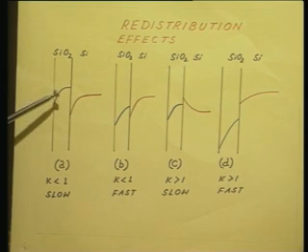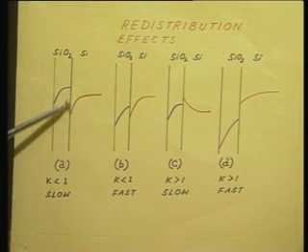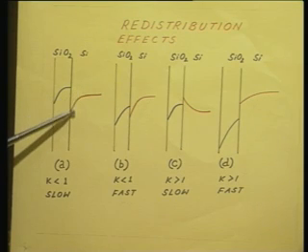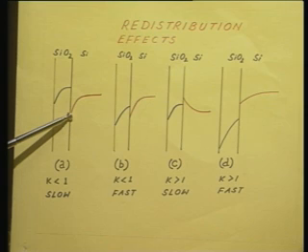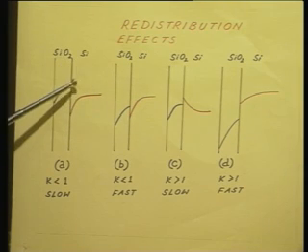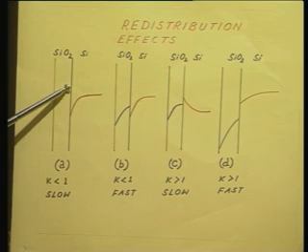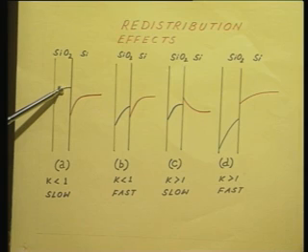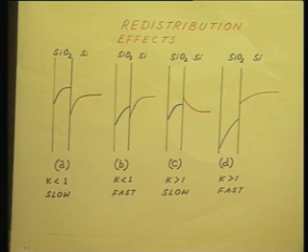Two facts you have to be very careful about, that is, at the interface, on the silicon side the concentration is less, signifying K is less than 1. On the silicon side the concentration of boron is less, as shown by the red line. On the silicon dioxide side it is more, and this concentration remains more or less constant over a considerable distance. That is because the diffusion is slow and then towards the surface it starts to fall. Okay. Let us look at a variation of this theme.